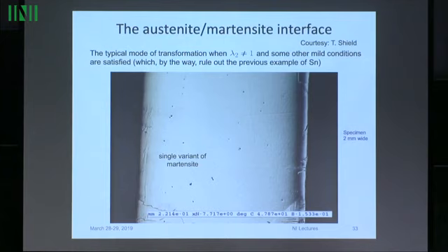And then we heated it. And so we saw the austenite come down from the top. Now it's all austenite. We saw the austenite come down from the top, and you saw a pretty typical austenite-martensite interface. The presence of the austenite caused microstructure in the martensite. In other words, in the disappearing phase. So that shows how strong compatibility is. It creates microstructure in the phase, not the new phase, but the phase that's disappearing.